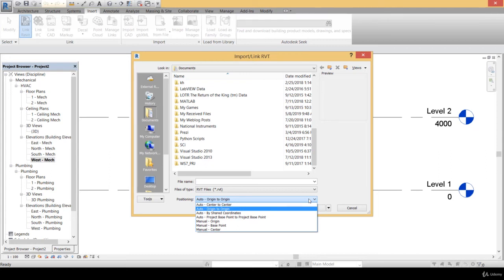So if you insert the project at a specific coordinate and another designer who is working on another part of the same project has inserted the layout at other coordinates with respect to the coordinates that you used, there will be a shift in the design between you and him, and this will be a problem. So instead of the manual insertion, we prefer the automatic insertion.